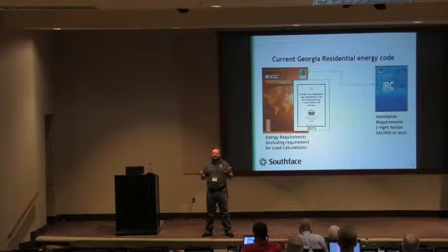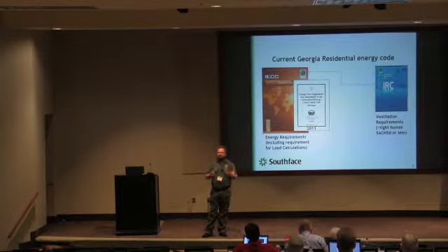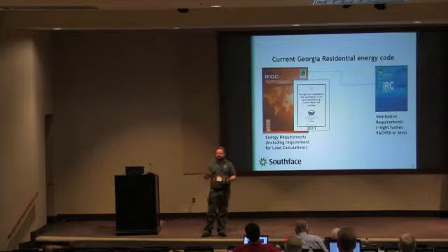Yeah. And that approach is not based on building science. It really isn't, right? Because he is taking a rule of thumb and saying, I think that this looks about right for the space that you want to serve, rather than assessing what's actually going on in the home. Now, again, if nothing else has changed, if you're doing a one-for-one exchange, there might not be a problem, but in particular, when other parts of the home are being renovated, when an addition's being done, when we're spray foaming a roof line, things like that, they really need to factor in the conditions of the home as it is going to be operating with the new system, or they can't right-size.